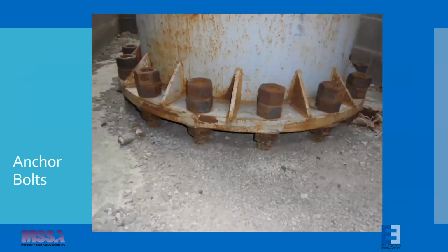Down at the bottom, you can see these anchor bolts. Two things of note from that. Grout needs to fill the entirety underneath the pole so that you can help distribute the load, but also the anchor bolts themselves need to penetrate at least 2 threads out of the bolts. There's a real challenge to fixing this one here. The grout would be easy to fill in and replace, but actually fixing a situation where the double nuts aren't fully engaged is a weaker connection. And so it can be fixed and repaired, but this is a challenging one.